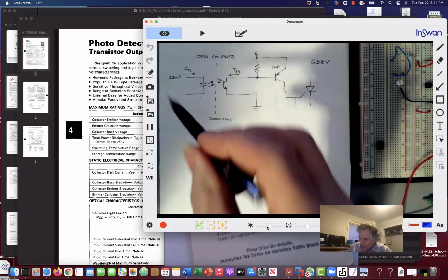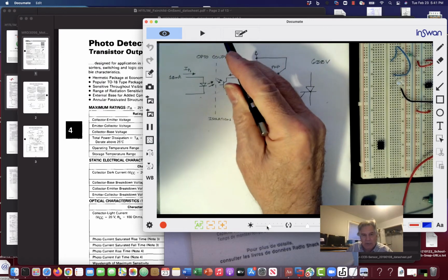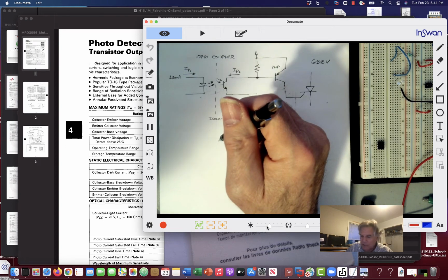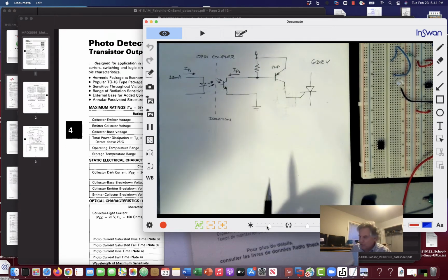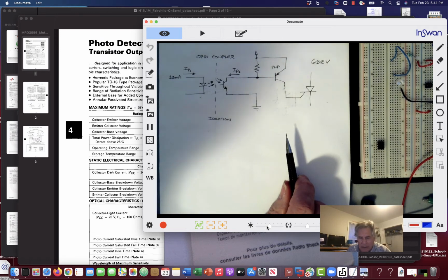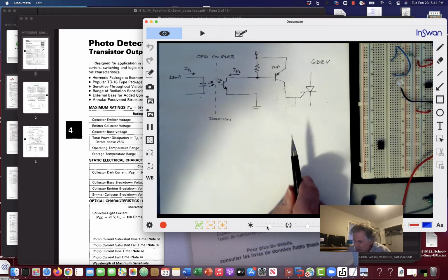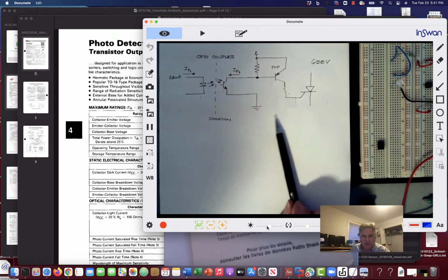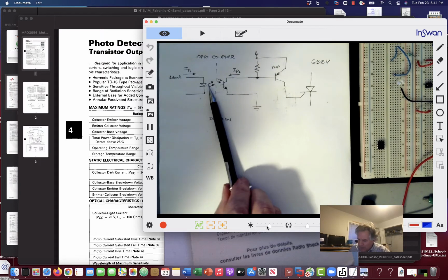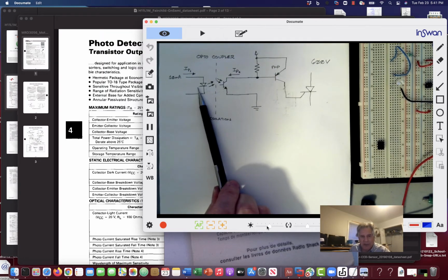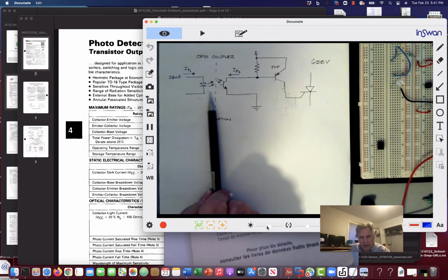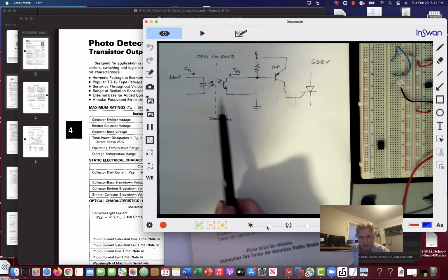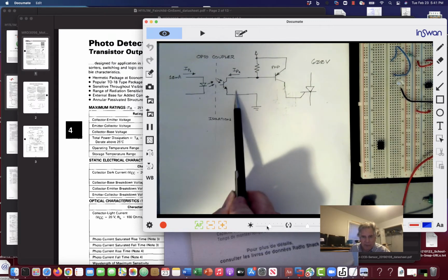And this might be some Underwriters Laboratories decreed boundary on which there can be no galvanic conduction. Such things exist. In fact, they exist in many what are called medically rated switching power supplies. The pulse width modulation to run the power supply is supplied across the protected boundary by optocoupler. You'll see some of those. They just have the 4 pins, because, like in this case, we really only need 4 pins.